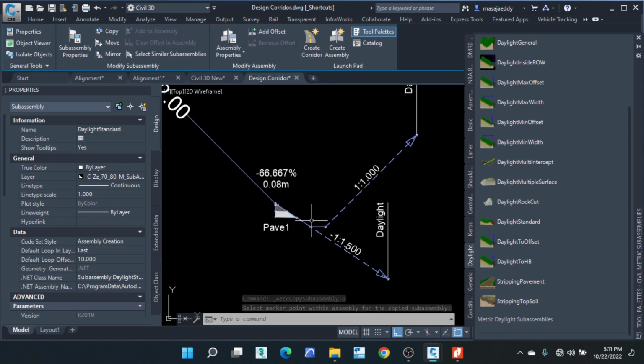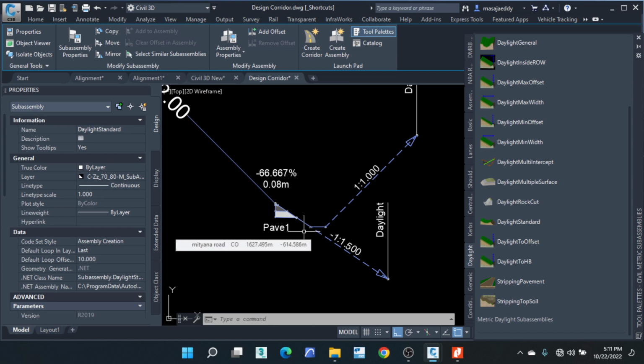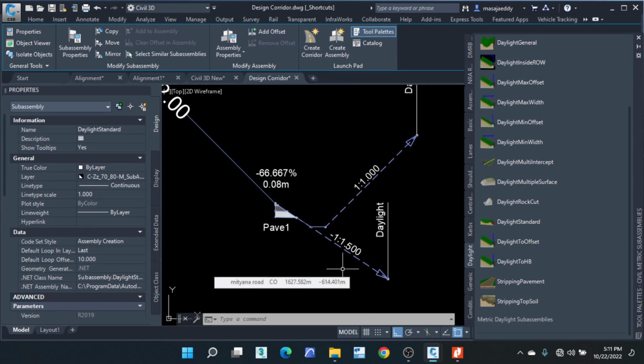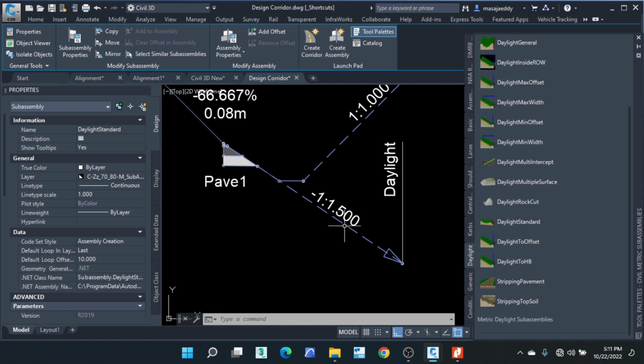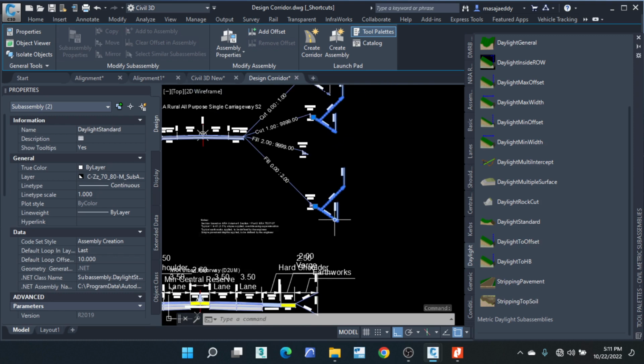In case you are filling and the ground is still sloping in the same direction, it just targets the existing ground the way it is. But in case you are filling and reach a ground that is moving towards the road, it will cut and insert a ditch at that point. That is why you're having a ditch here. I think this one remains the way it is.